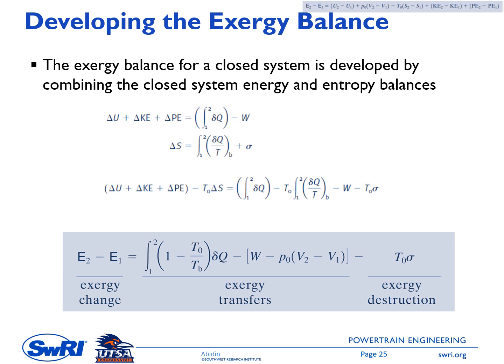So the energy balance for a closed system can be seen in this first equation. The left side represents the change of the system energy, consisting of the internal energy change, kinetic energy change, and potential energy change, so delta U plus delta KE plus delta PE. It is balanced on the right side by the energy transfer in terms of the heat transfer, and also by the work. This formula follows the convention in THERMO 1, I believe. If the heat transfer is going to the system, it is positive. If the work is done by the system, it is positive.